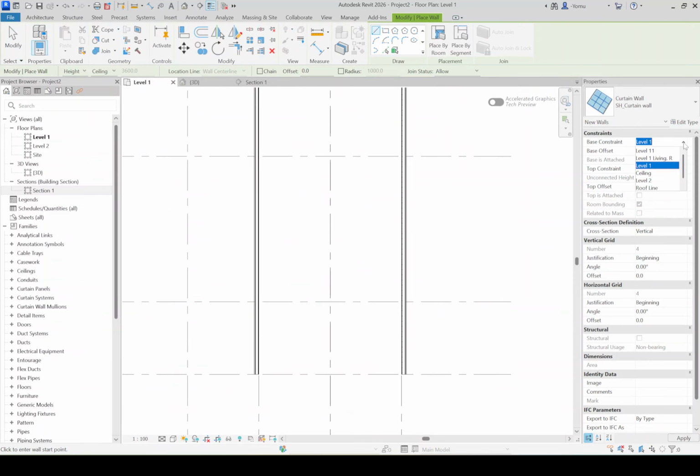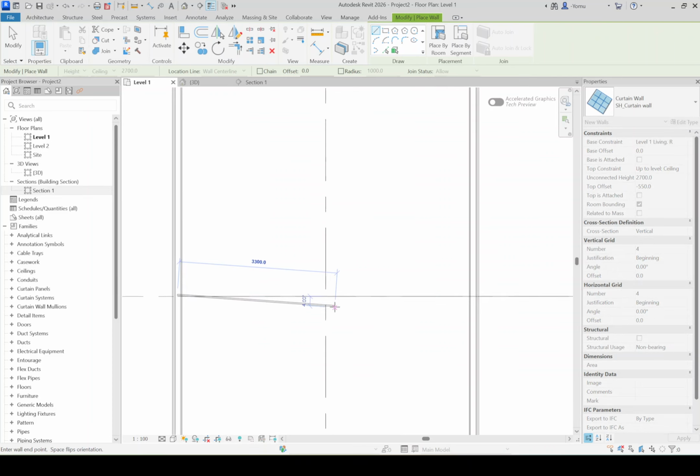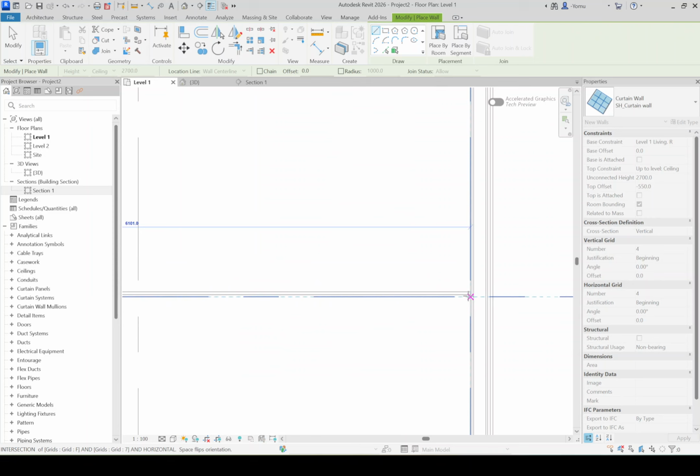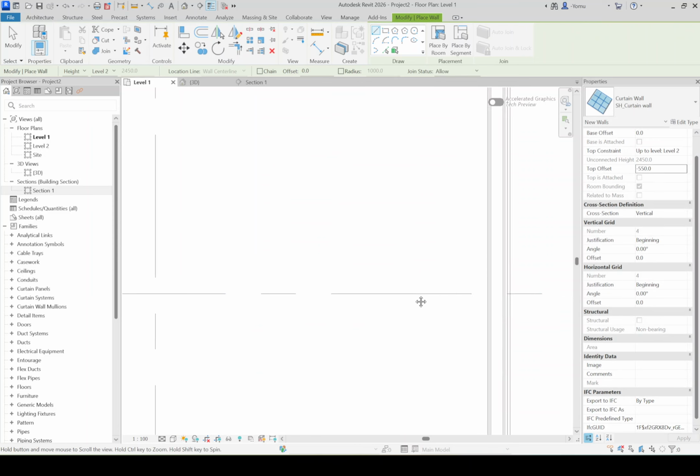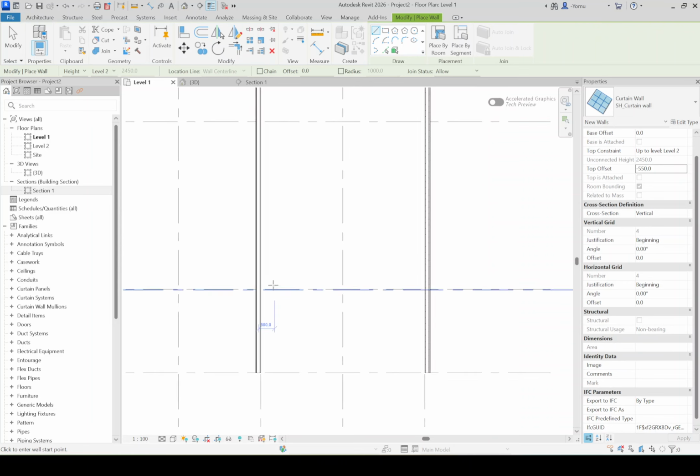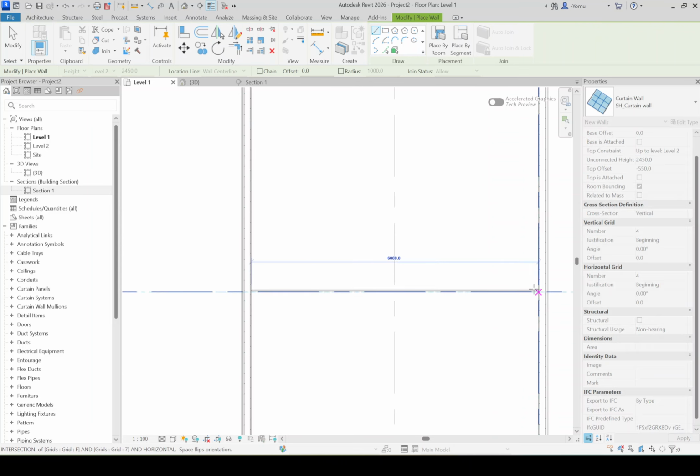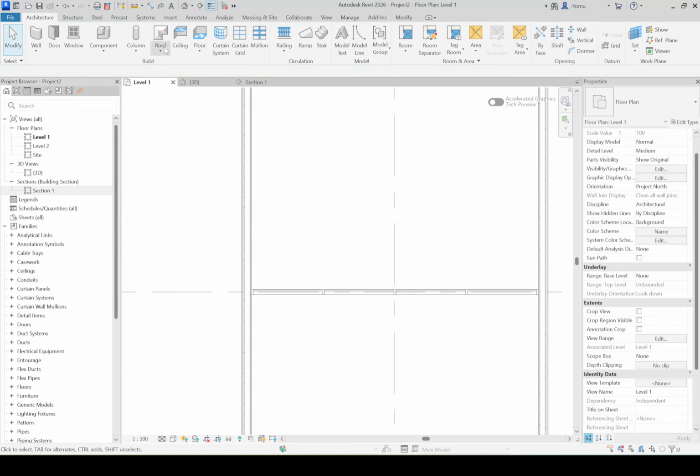So instead of level 1 now, we will go to living room, no offset to the ceiling, but here, as I remember, we have minus 550. So create it now. I think we'll have to also choose, no, it should be, everything is correct. So, like so.